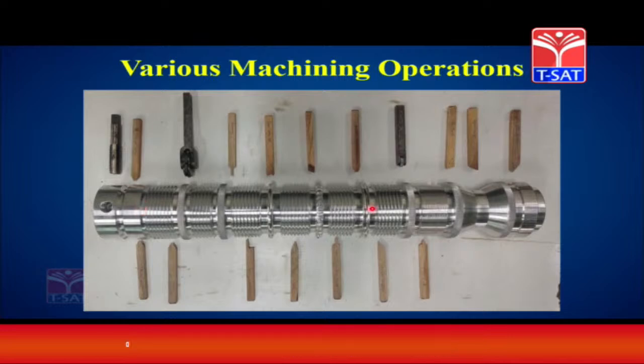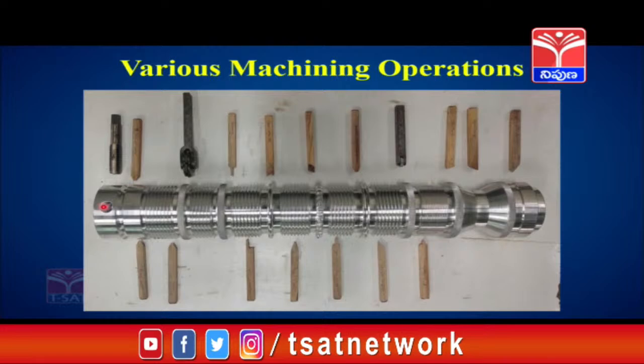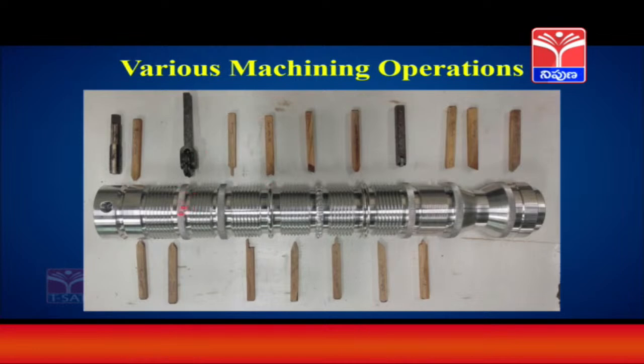Here you can see each and every operation we have given the space, in the form of grooving, and then after plain turning, and here you can see V pulley drive, and of course we have done the drilling and the internal threading. For drilling and internal threading we have used the drilling machine; except for all the others we have used the lathe operation and a single point cutting tool, except this knurling.